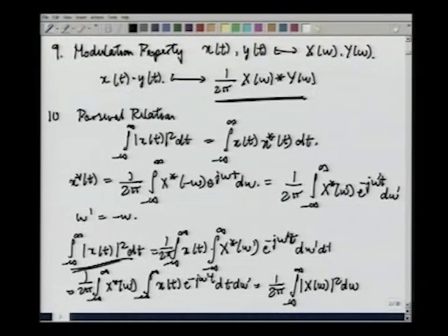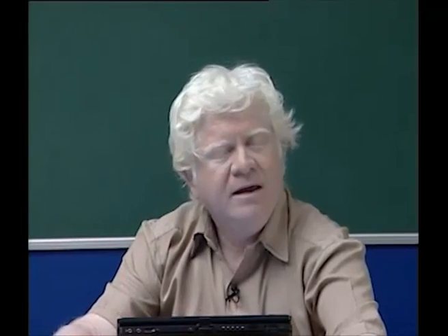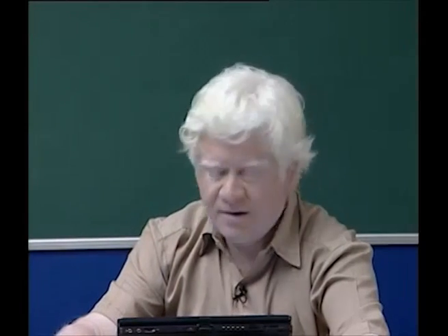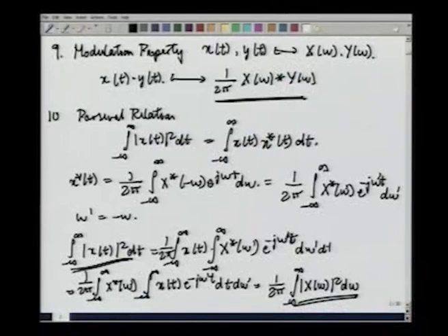So, we have that this equals this, which is what is called the Parseval's theorem. Now, this is the energy in any function x t, and if you have a function x omega, the energy in that is given by integral mod x omega squared integrated over all omega. It turns out that the energy in x omega is related to the energy in x t through this factor 1 by 2 pi. That is essentially the statement of the Parseval's theorem.